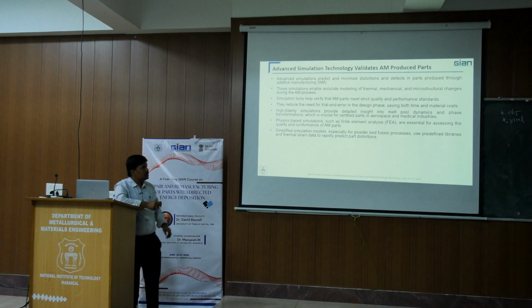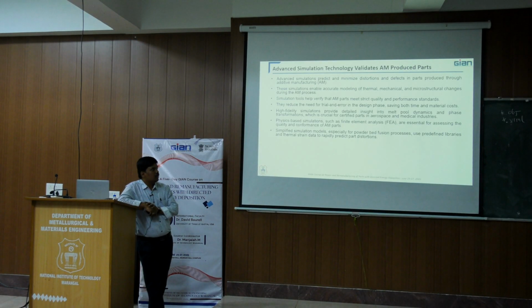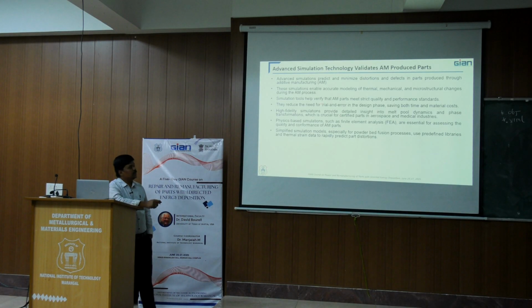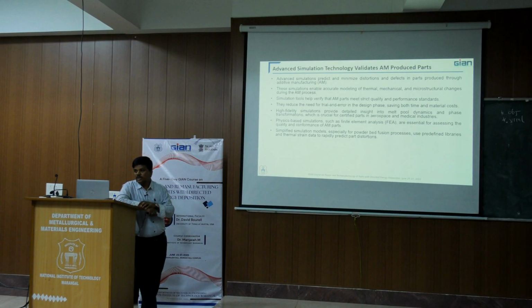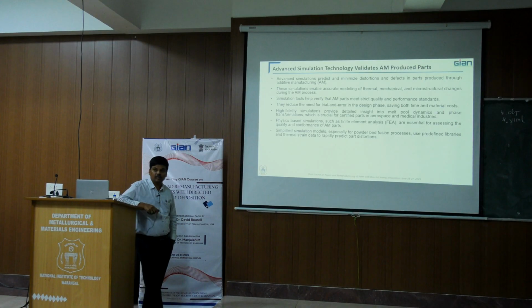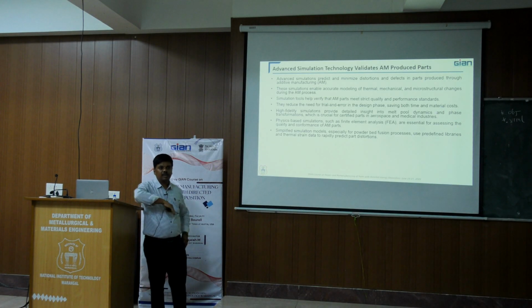There are simplified simulation models, especially for the powder bed fusion process, where predefined libraries will be there, and even the thermal strain data will be available, because nowadays for PBF a lot of work has been done and numerical studies are also done. But with respect to DED, very minimal work. They are trying to adapt our welding technologies, how we have done for TIG welding or MIG welding.